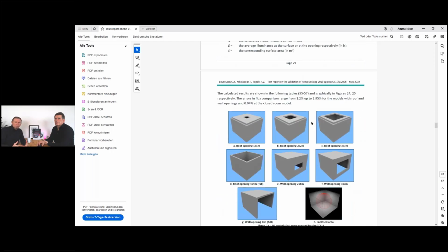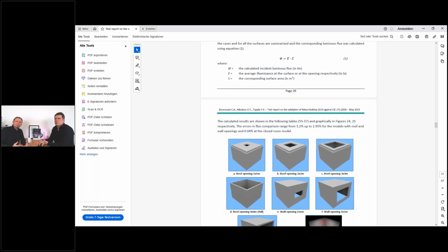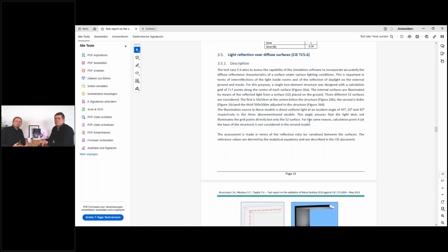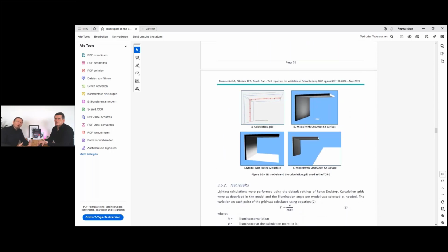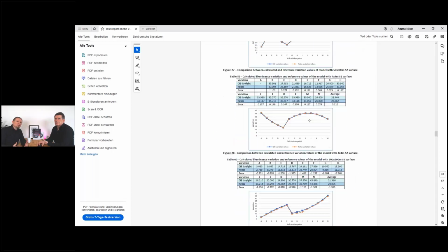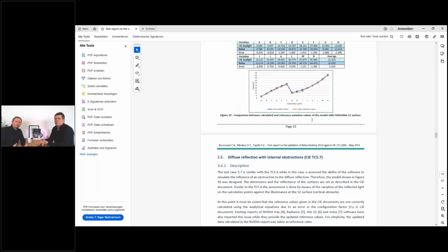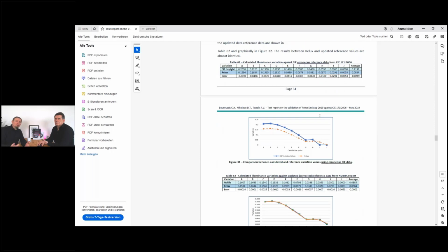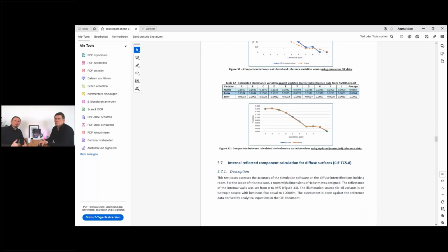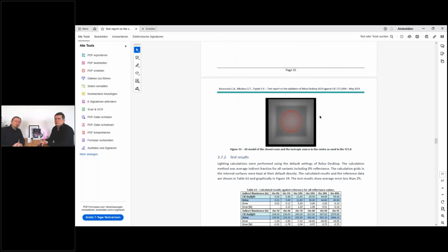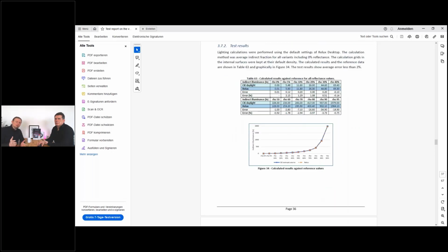And this is quite okay for light. So it's not visual at all. And this is also good to keep in mind what you are doing. You have a tolerance bandwidth if you model everything really accurately to the real life situation, then you end up still with 10%. And luminaires can vary it. So not any LDC measurement is a sample for all the luminaires from the same series. There are also tolerances in creating luminaires.